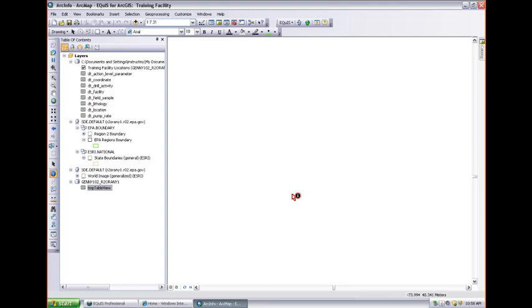Then you don't have to access the individual tables because the reports handle all the complex relationships between them. If you were to do it manually with the raw tables, for example, if you open up like DT, like aquifer tests, there's no XYZ column on that, right? So you'd have to do all that joining and stuff in the ArcGIS environment. So it brought in, like I said, just every populated table.